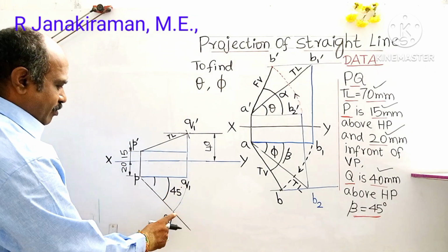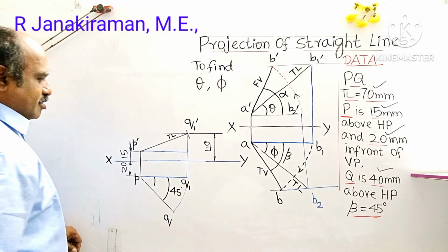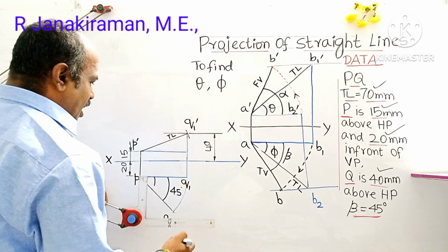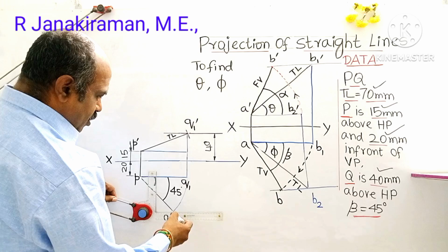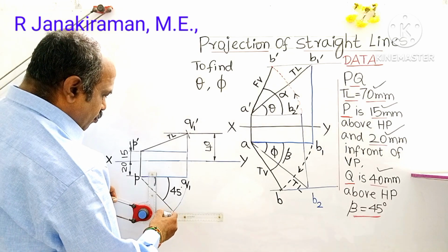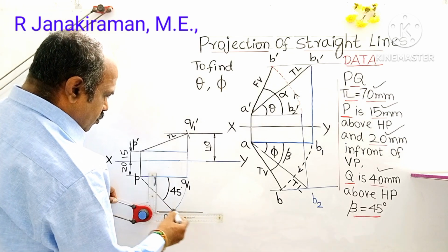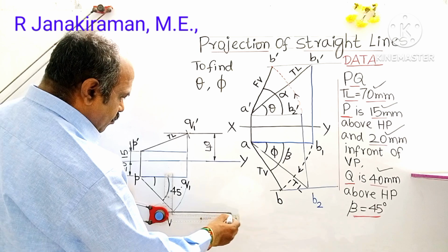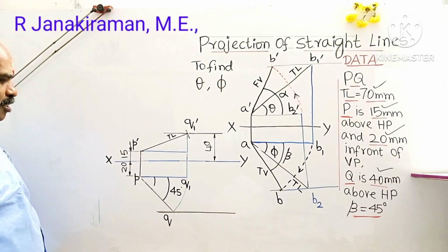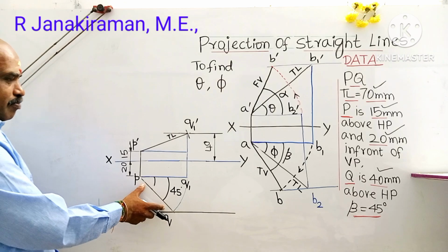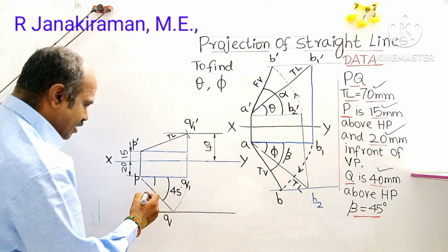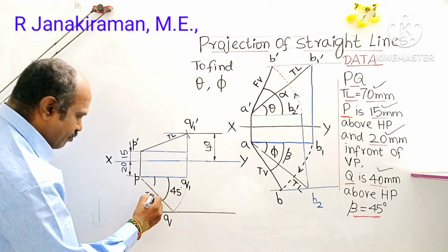Okay, this work is remaining length, you can erase it. Okay, so then you use it to draw a horizontal locus line passing through Q. This is B, here it is Q. Draw a horizontal locus line passing through point Q. Okay, so next we know this is the top view obtained. PQ is the final top view. Here it is AB. So we will read it as TV. Final top view is obtained.